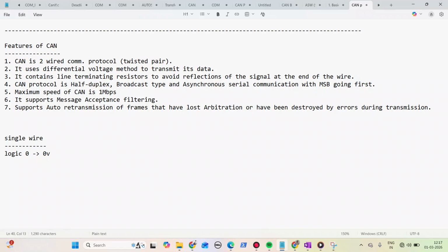So in our car, due to that electromagnetic interference, voltage is being induced. Because of that, instead of 0 volts, voltage is getting induced inside that single wire, and for example, consider it became 3 volts.